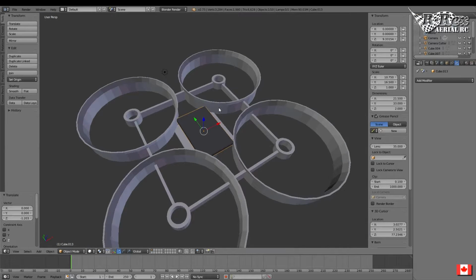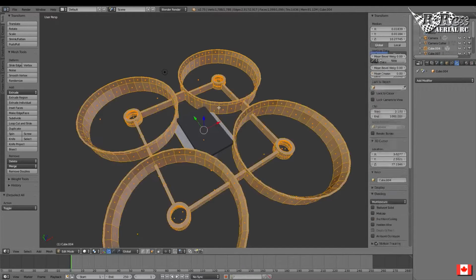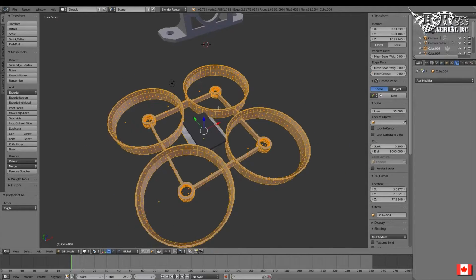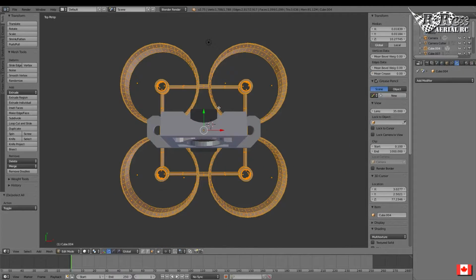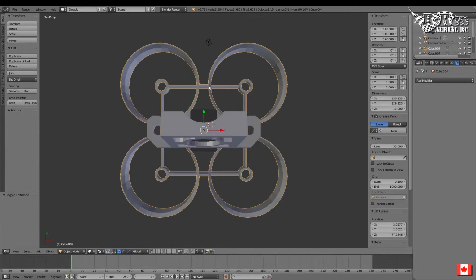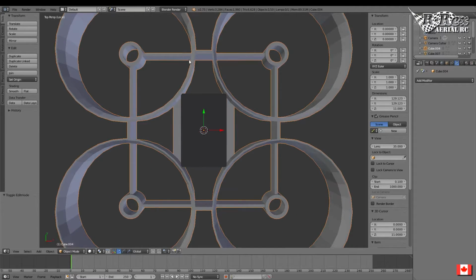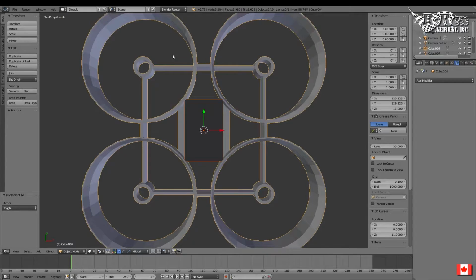Okay, do you know what? Originally, because my design was quite a bit more complicated, here we're going to make up our space differently. Our object is centered, so I'm going to press Tab, then A to select everything, then 7 to give us the top view, and I'm going to isolate. There we go, everything's isolated. I want to actually grab the flight controller as well. Done. I'm going to isolate those two objects, press 7 to get our overhead view, and press Tab.